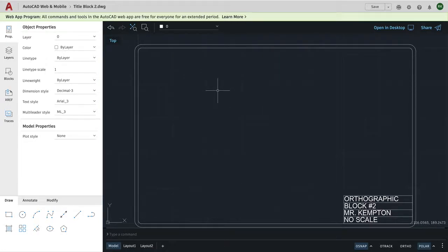Now we're going to add one more layer, pardon the pun, to the complexity of this drawing by creating layers. And layers is a way to control different aspects of your drawing. For example, if I was creating a house plan in CAD, I would create one layer for all of the walls and the framing. I would then create another layer for the plumbing and a different layer for the electrical. And then you have the ability to turn on and off these layers and look at only that component of the drawing. But it also allows you to control the type of line you're going to use. You can use dotted lines, different colors for different components of your drawing.